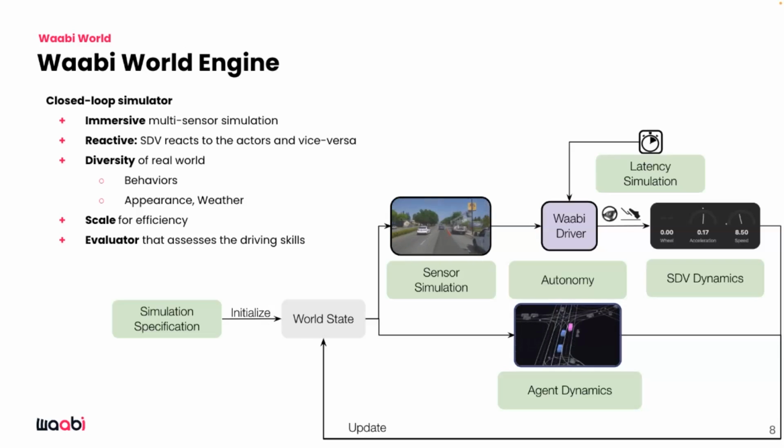Another aspect of simulation that's not often talked about is latency. For example, on a particular truck compute or vehicle compute, it takes time for the autonomy system to take the sensor data and generate actuations. This type of delay is very key to measure and model in order to have strong bounds on the reaction performance of your self-driving vehicle. Oftentimes you're running your simulation system in a software-in-the-loop setting. So you're running your simulation and self-driving autonomy system on cloud compute, which is not indicative of the actual hardware compute you run your autonomy system on in the actual self-driving vehicle. So you need to model and estimate how long it takes to run different modules of your autonomy system and how long it actually takes to generate those final actuation outputs. That's a key part of latency simulation.